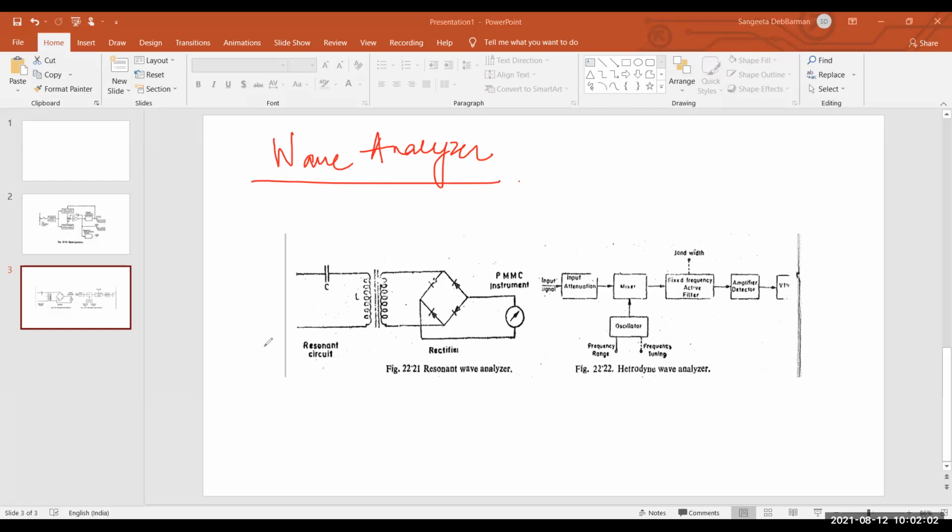Now, graphical and mathematical methods may be used for this purpose, but these methods are quite laborious, meaning they need some time and much effort. So analysis of a complex waveform can be done by electrical means, using a band pass filter network to single out the various harmonic components. A network of this type passes a narrow band of frequency and provides a high degree of attenuation.